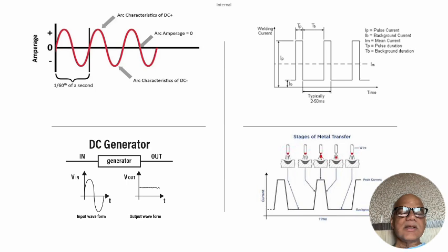The second advantage with the electronic control is that we are not only able to rectify it, but we are able to modify the sinusoidal pattern to a pattern like what we are seeing here. It's almost a square wave pattern that we get, or we can get it with a little sloping up and down, so that we get good detachment of the weld pool, or detachment of liquid metal from the wire towards the weld pool.